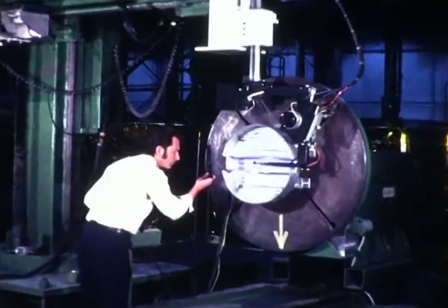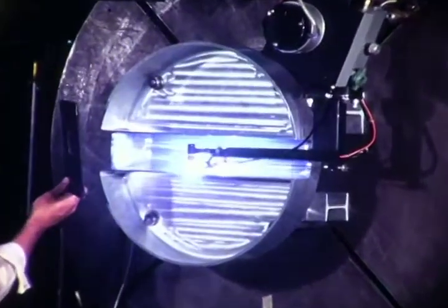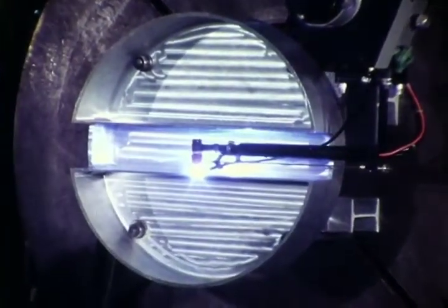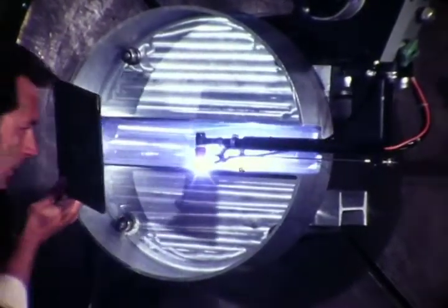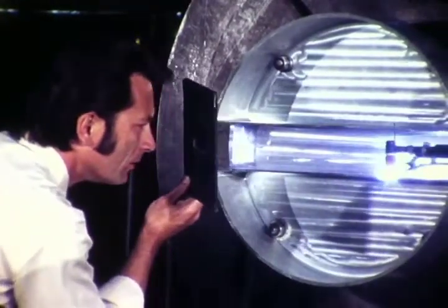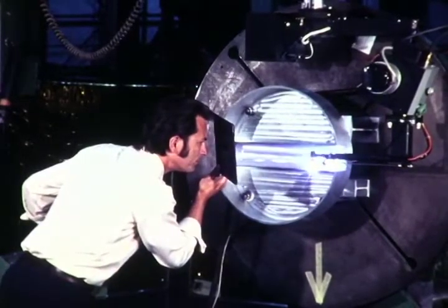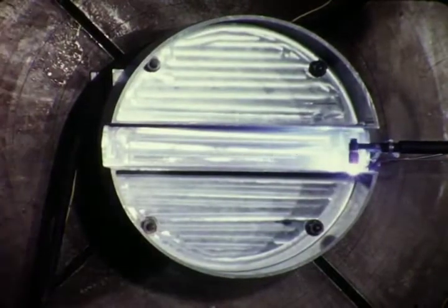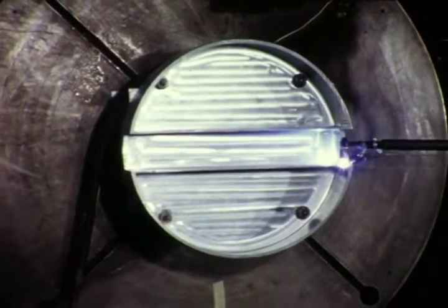The mid-body section, which will contain the missile's folding wings, again gets a bulkhead welded to each end. But it has 2 girth welds at each end, joining 2 D-shaped cylinders of the center section to the bulkheads. A weld certification specimen simulating one end of the mid-body is being welded here. The weld pass is started inside the wing slot, where it will overlap at completion. A torch arm of smaller profile is used in this restricted area.